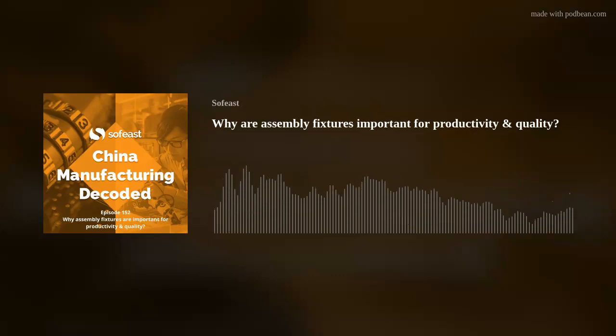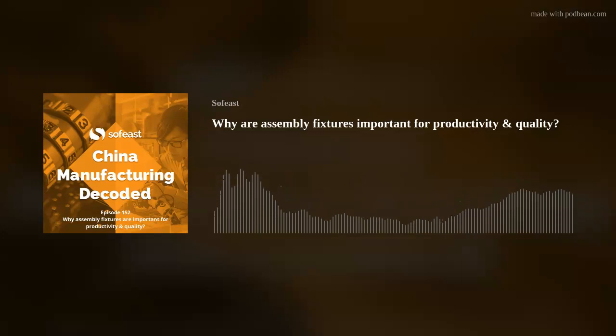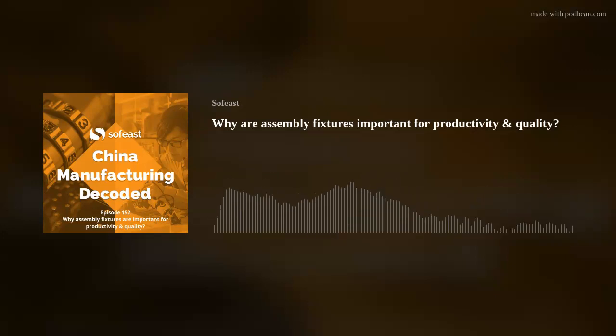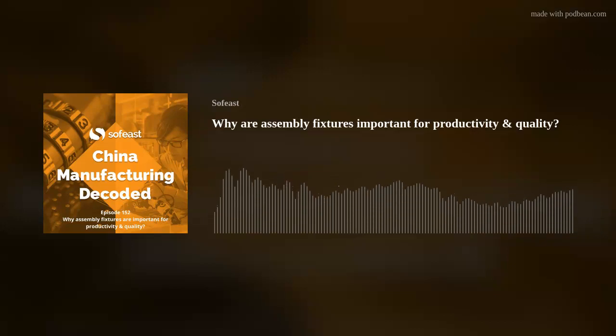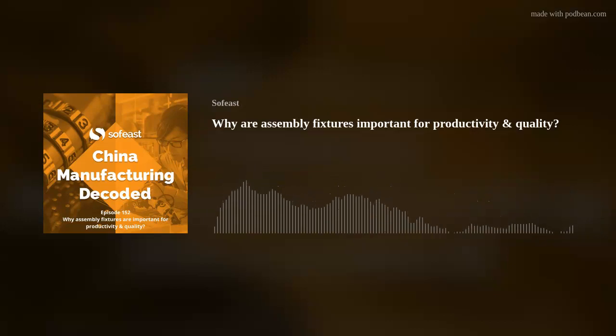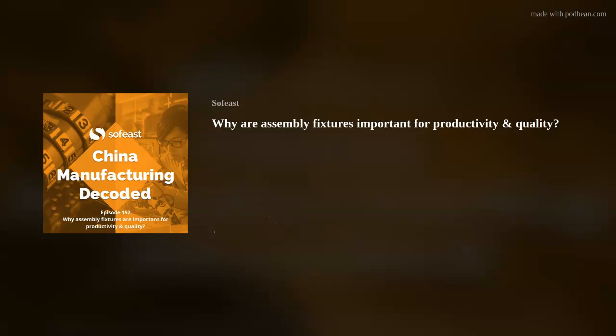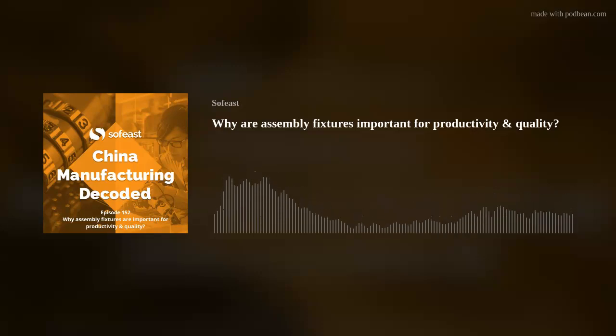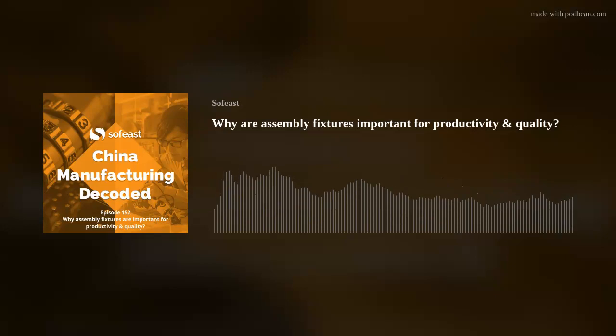Another very quick and easy way is to put the PCB on what we call a bed of nails. Basically it's a set of spring-loaded pins, and we call them pogo pins. You put the board down, then close the lid or push down, and the pins contact all of the key contact areas. Now, most PCBs have got test points on them, and it's easy to test whether that PCB is good or bad before you assemble it. ESD, electrostatic discharge, that's the one. Well done, Renaud. We got there in the end.